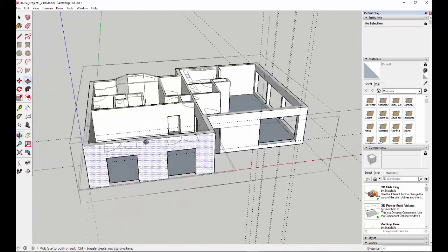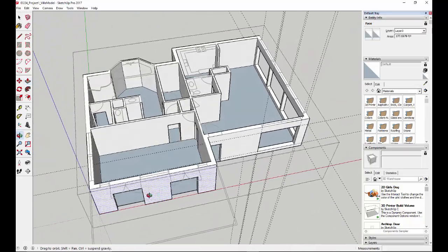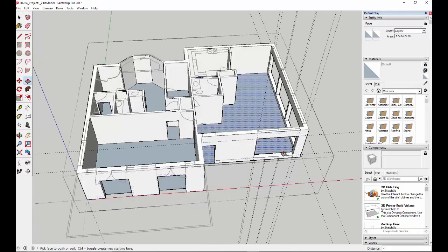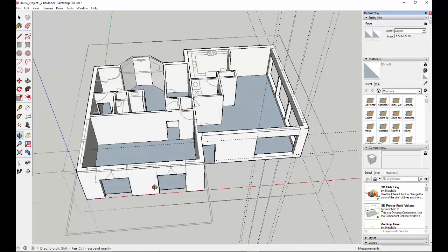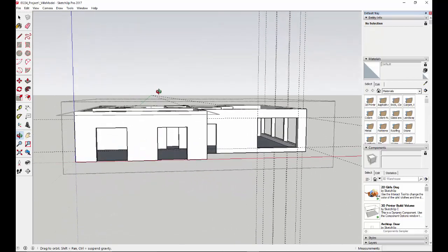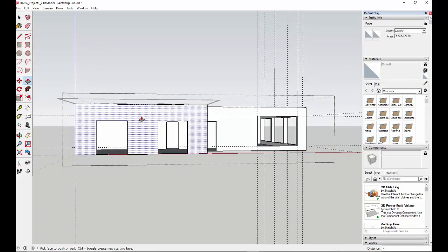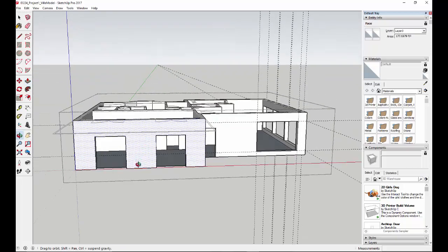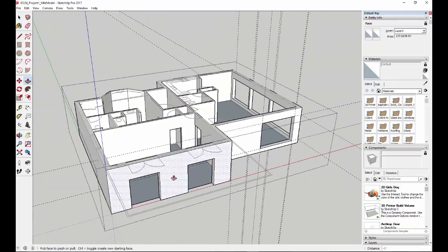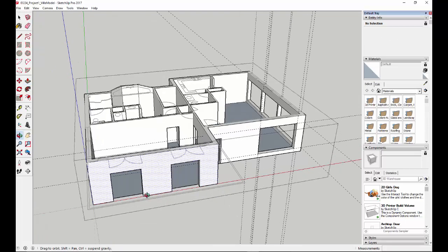These windows, however, that are located around the rest of the house are not quite that tall, and they do not have the same sill height necessarily. Maybe you want them to have it that way, maybe you don't. So we're going to play with this a little bit. Most windows on homes are actually, the header of the window is the same height as the doors. They like to make things align quite a bit. So you can decide how big you want the sill to go. Maybe I want mine to go a little higher. I think a typical height is somewhere between 2 foot and 3 foot for window sill heights.